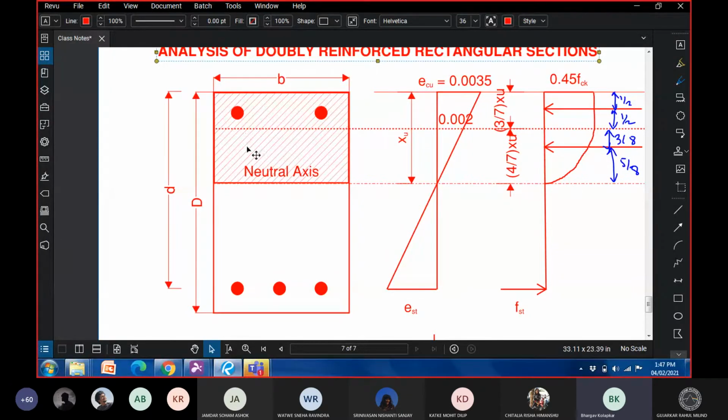So there's something called a stress reversal in a beam. You're not certain that the sagging moment will always be at the center and the hogging moment will always be at the supports. Or to put it in other words, you cannot be sure that you will always require tension reinforcement at the bottom of the beam. You might also require it in the top at the center. So this particular answer has a very specific application. Okay, so in general, in gravity design, when do we use doubly reinforced beams?